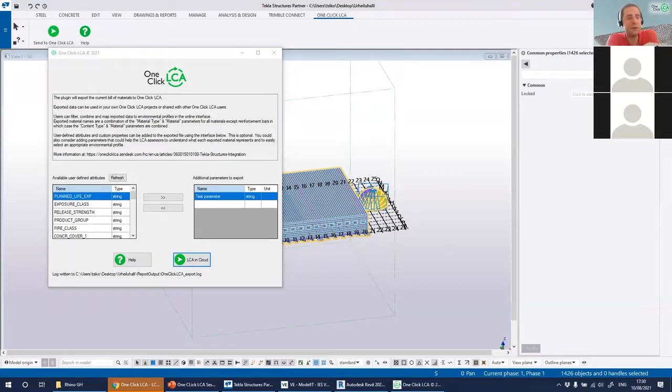find all the different materials, as we saw, by isolating the materials. If you remember that button in the LCA in Revit plugin, find all those materials. You can click on edit type for those types, and you can check all the different information that is in there, like the type comments or type description and the various materials that are within that type, for example.